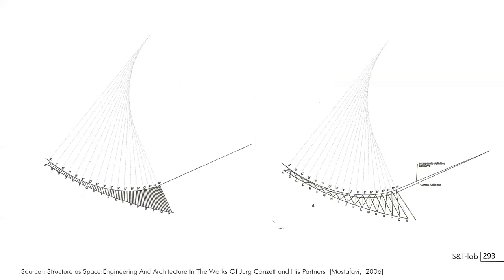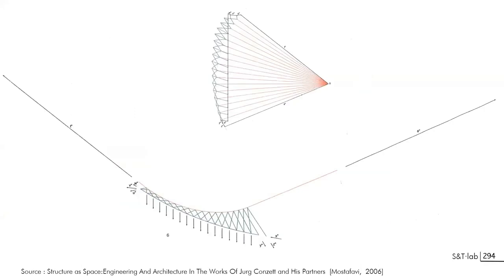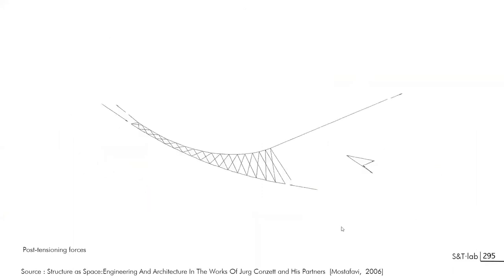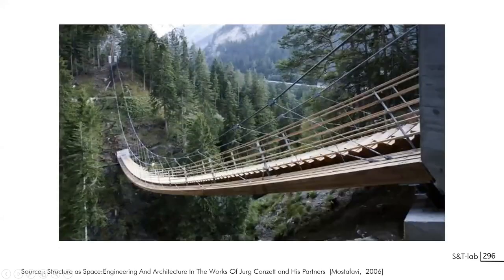So you will see here an adapted force polygon and form polygon for this example. And just to show you that the pre-stressing can also be represented by a closed force polygon here. Just to say about this result, this is about design, and graphic statics helps you to define the geometry.